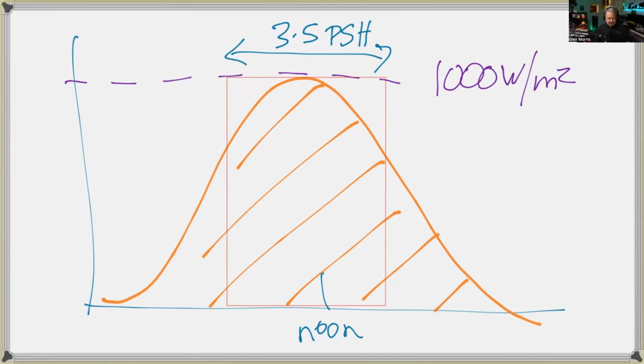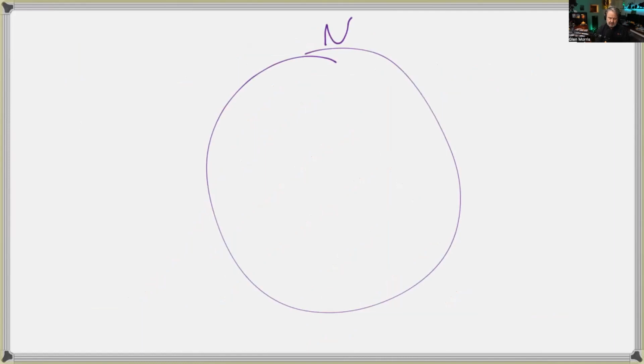Now, I used to have a tool that could generate this, and I've put quite a few of them in the Dropbox for you under solar radiation data. So there's quite a few sites where I've generated data on a monthly basis for every angle of inclination and azimuth. And so I better explain those two terms. If that's a compass, and that's north, and that's south, and that's east, and that's west, and you want to describe direction, a more accurate term is to talk in degrees of azimuth.